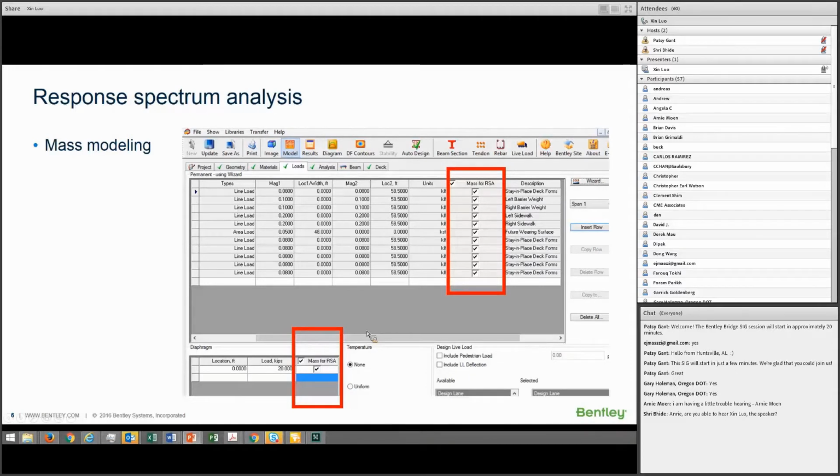Once this adjustment of the mass modeling is done, you can run analysis in this module, then exit this Superstructure Module and return to the main module and update the LBridge Concrete model accordingly. So the data brought back to the main module include the analysis of this Superstructure Module as well as the mass table of this superstructure.